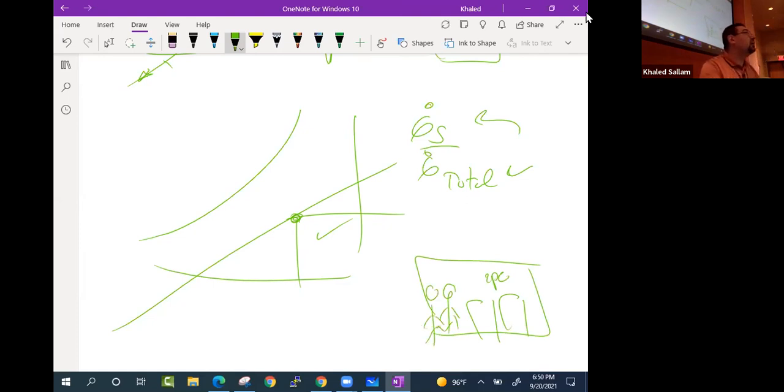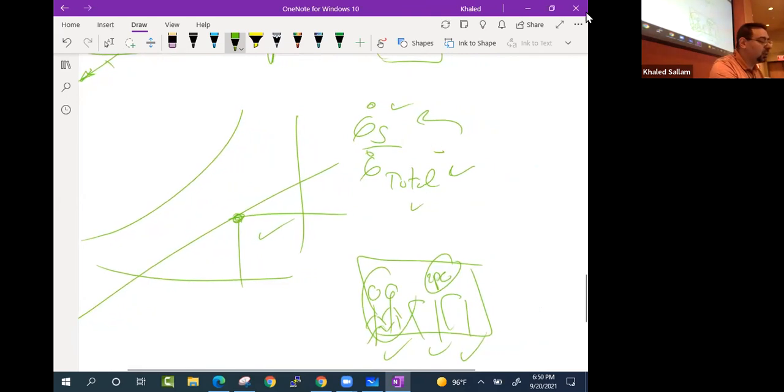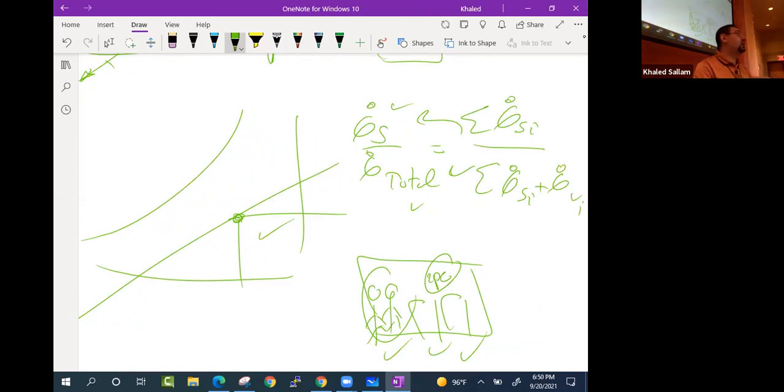Okay. And there are tables to tell you, I will show them to you next, that will tell you those equipment will generate this much Q dot S and this much Q dot L. So you will have to do the sum over i of Q dot S,i over Q dot S,i plus Q dot L,i. And you add those guys.